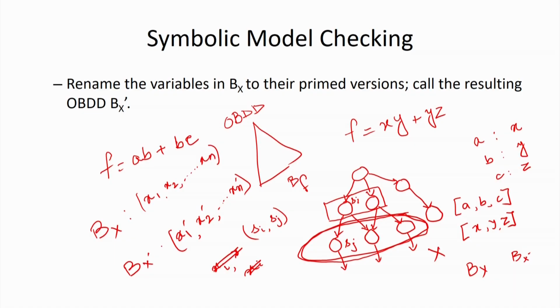You just see this transition; I have to concentrate on this transition to find out the predecessor of this particular state S j. So, this transition is represented by present state variable and next state variable. So, that is why we are renaming the variables of this particular state by the next state variable, and now the other state S j will map to this particular Bx.